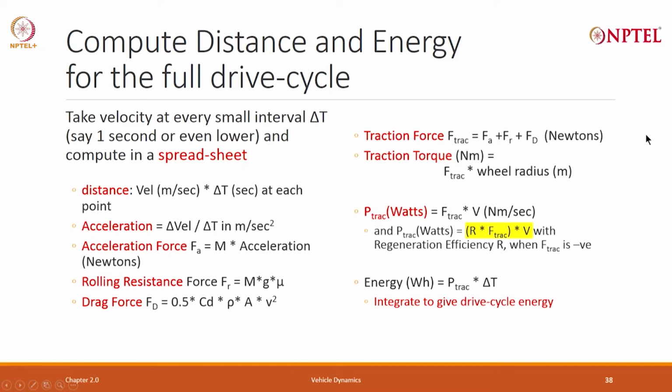All right. Now, if you notice in this, what I have not done is the slopes, because the Indian drive cycle does not define the slope. But in one of the assignment problems that I gave you, I actually included the slope. So, the spreadsheet will change a bit. We will include one more force called the force due to climb, the force due to gradient, and you have to add that and do the needful.